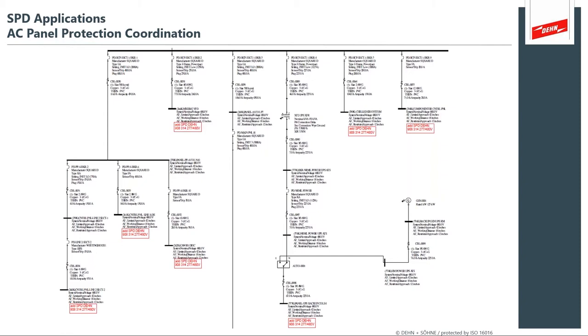You have an upstream device, you have some distance between the upstream and then the downstream surge protection devices. The standards do a really good job describing the distance to pay attention to. It's generally anything over 10 meters. We'll pay more attention to that in some upcoming slides. But what's really important is to analyze your schematic, understand the voltages that are at your distribution panel.